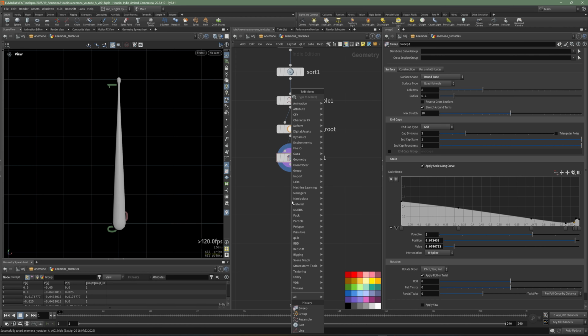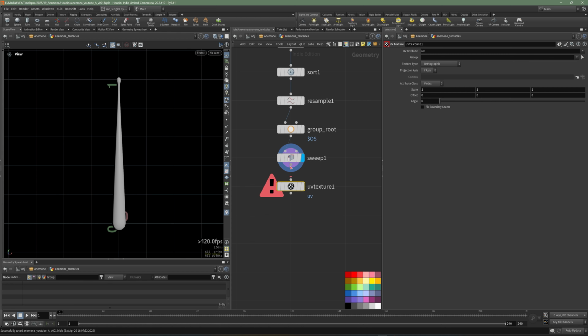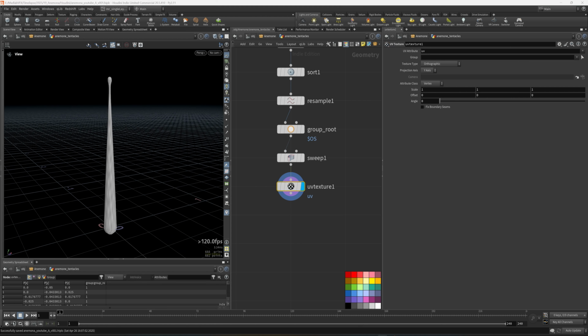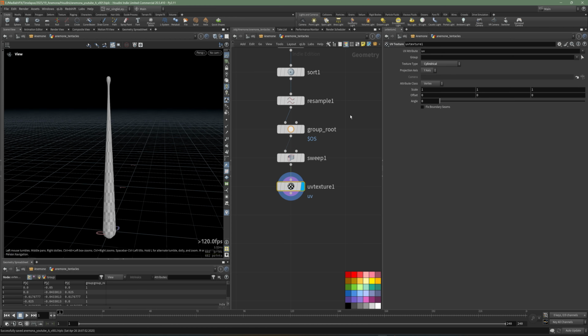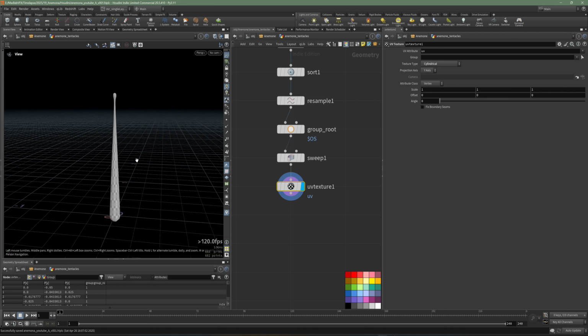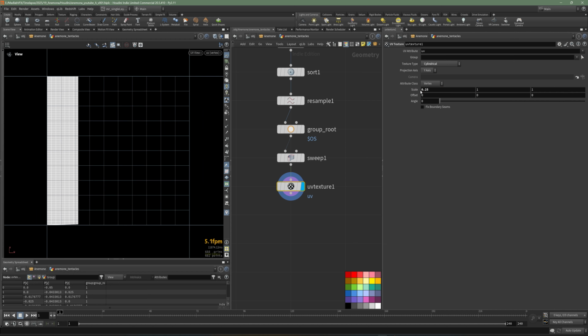Now you just need to create UVs for the shader using a node called the UV texture. This texture here should be in cylindrical projection type. Let's see the UVs. You press space 5 to see the UVs and change the scaling X to like 0.25.